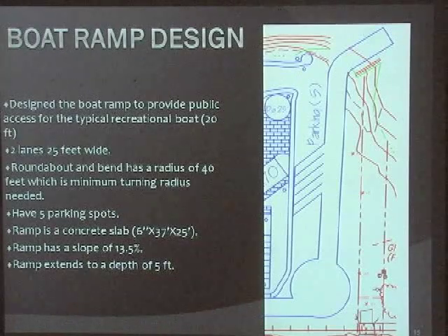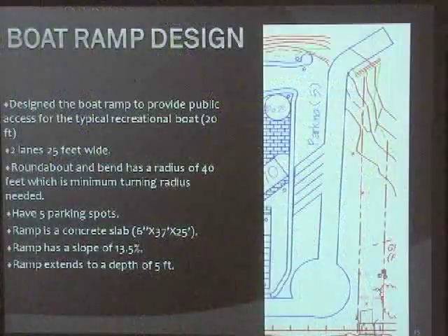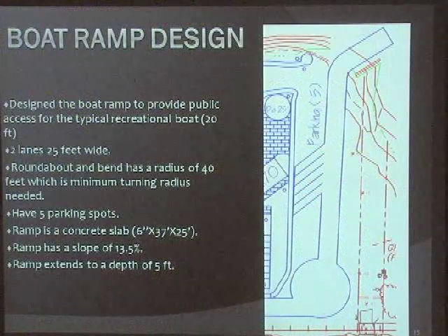The boat ramp is actually a concrete slab. It has a slope of 13.5%, which is within the requirement of 12 to 15%. It also extends to a depth of 5 feet, which is needed for boats to be launched properly.